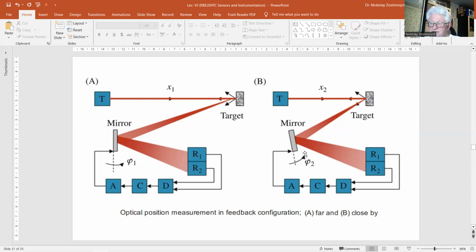on the right side, where the photocurrents become equal again. The control signal for the angle is a measure for the displacement. By feedback, the requirements to the source and the sensor are reduced significantly, as explained in